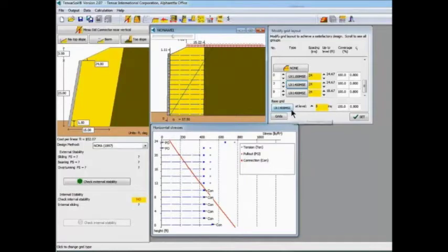Let's first adjust the grids at the bottom, and we'll work our way from the bottom of the wall to the top. So we know we need to improve this layer of geogrid, the base geogrid. So let's click on the 1400 MSE label, and now it will be UX 1500. You can see it is now changed to a pink layer of geogrid, so you can differentiate it visually between the different types of geogrids. This one is now satisfactory.